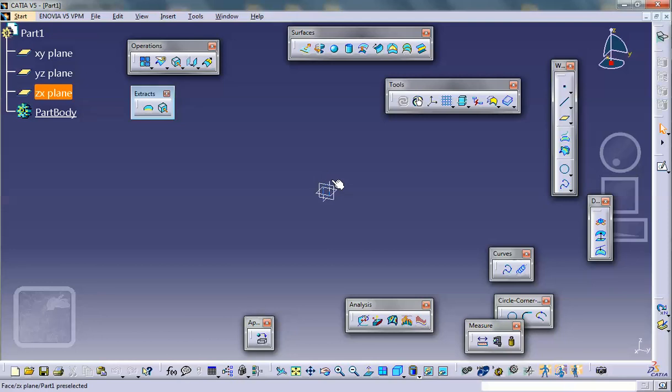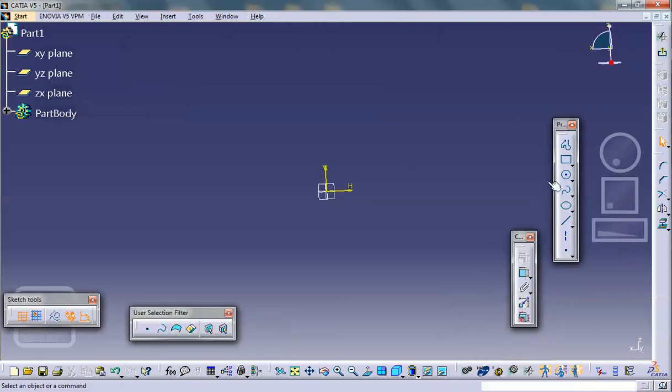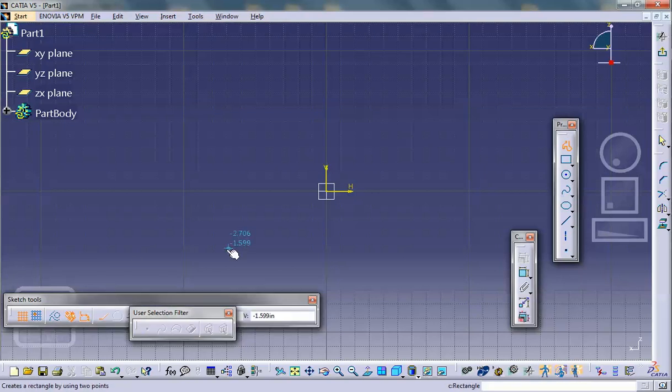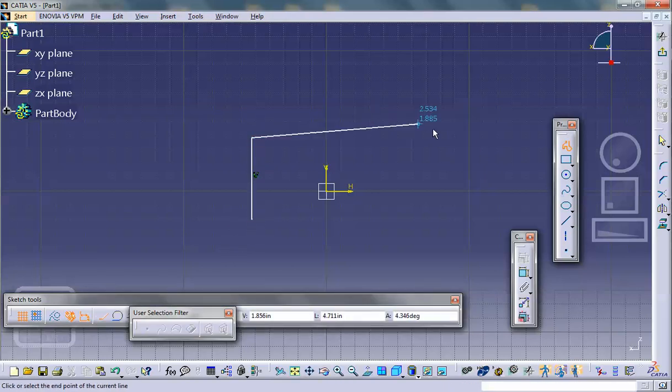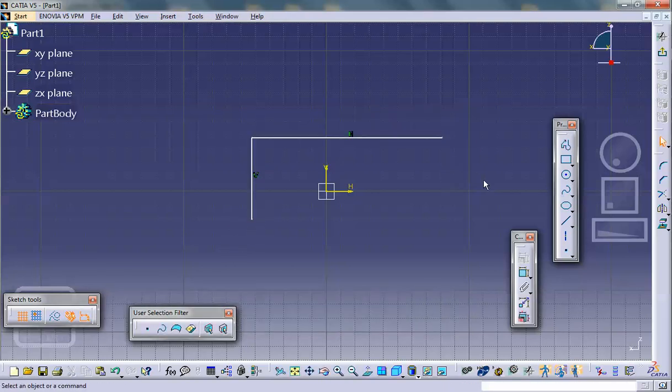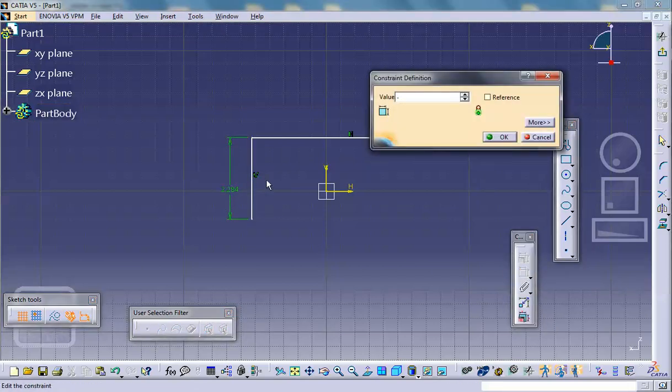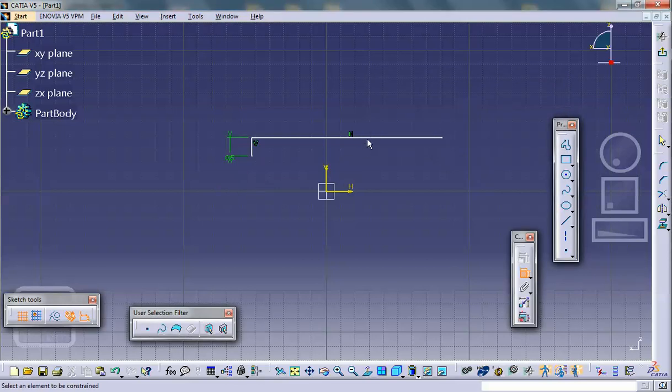So on a particular plane, such as the exit plane here, I'm going to sketch the cross section of that folded sheet metal, which looked like this. Let us give it dimensions so that it agrees with what we had before. So this was 1/2 inch, 0.5, and this one was, if I'm not mistaken, 1 inch. All right, exit, and then extrude it.